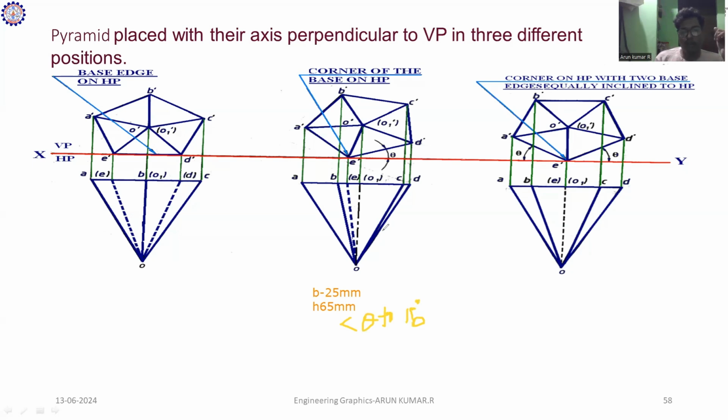So first of all, what do I do? First, you place the point over here. After placing the point, you proceed with the angle mentioned. That is only for the orientation of the solid. It will look like a front view. So 15 degrees, you mark it as 15 degrees. This is the 15 degrees.